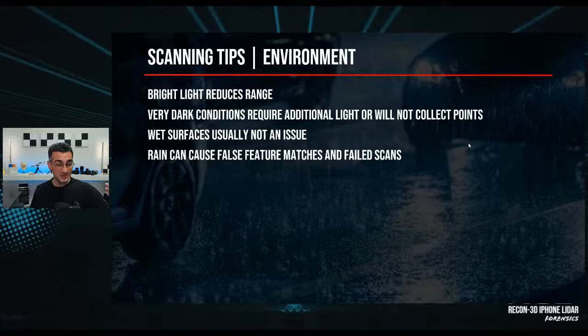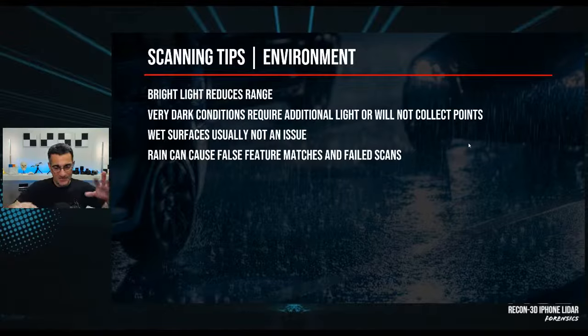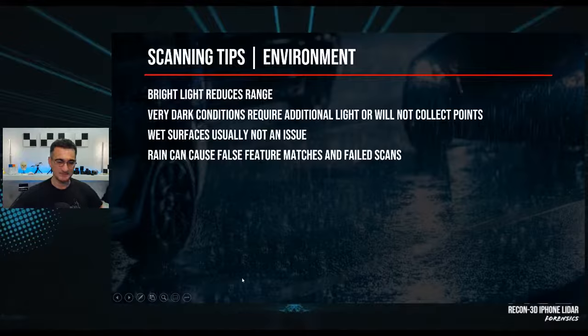But those raindrops were causing false points. Basically it was grabbing onto raindrops, so I wasn't picking up a lot of good feature points for tracking and things like that. Heavy water is also going to cause a little bit of havoc for the LiDAR. If it's spitting rain or something is wet, it's fine. But if it's really coming down, with big drops getting stuff messy, or you have puddled water, probably not the best scenario.